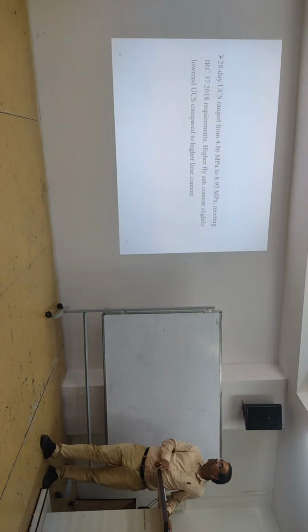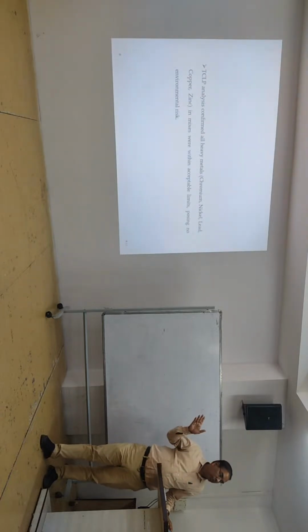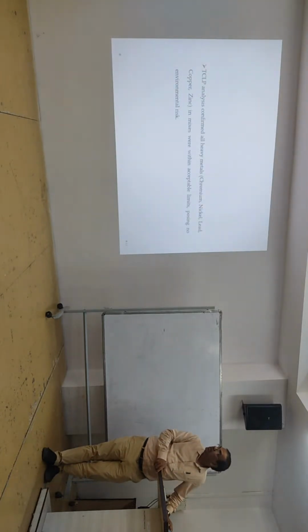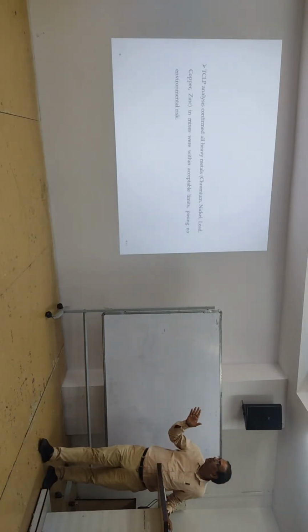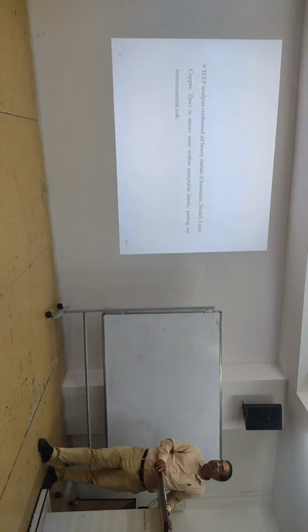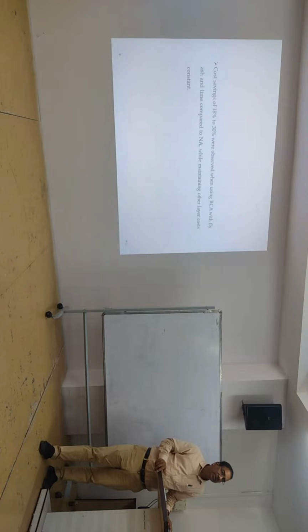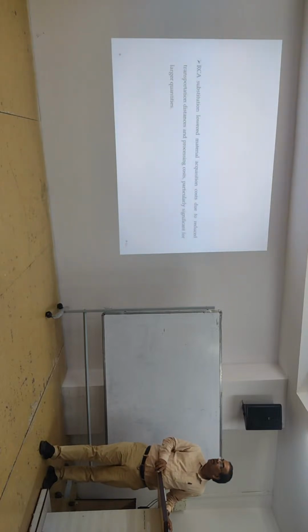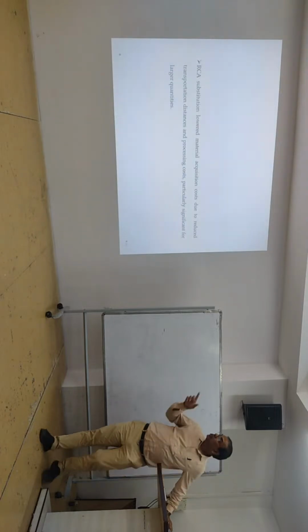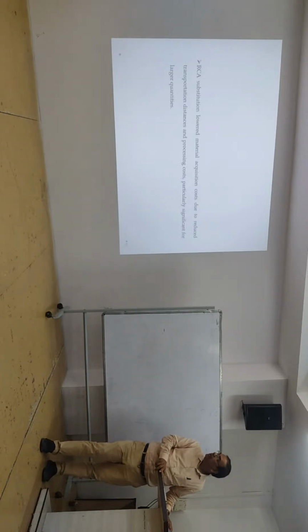The strength is also increased from 8.86 MPa to 8.95 MPa. That also you can see in the TCLP analysis, which means whatever materials are there, we got them within the limits, posing no environmental risk, and there is no risk at present. We got cost saving of 18 to 30% because of RCA with respect to natural aggregates. So RCA substitution lowers material acquisition cost; that is what we have done.